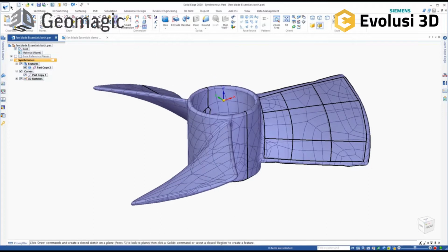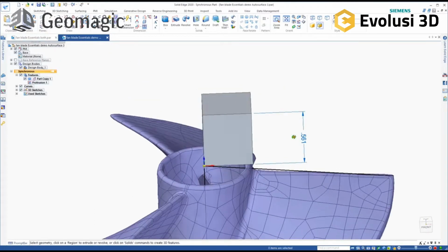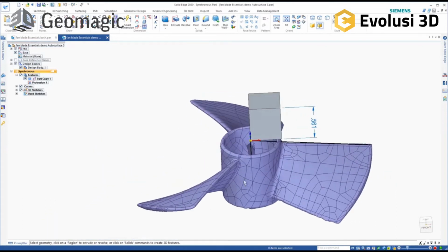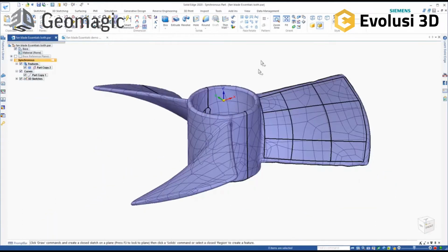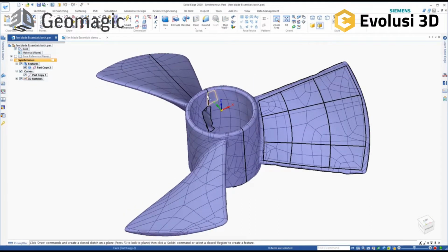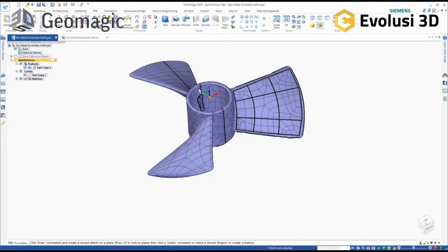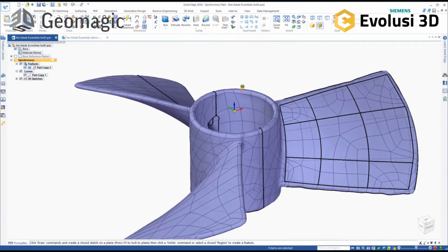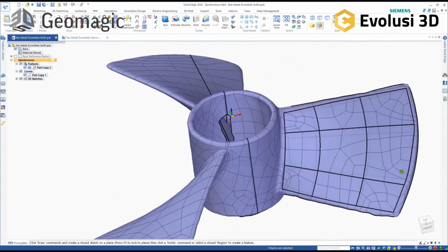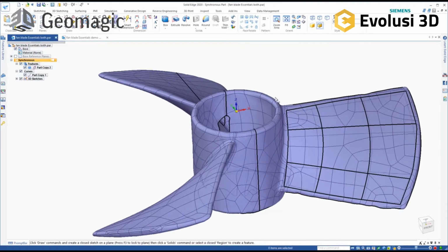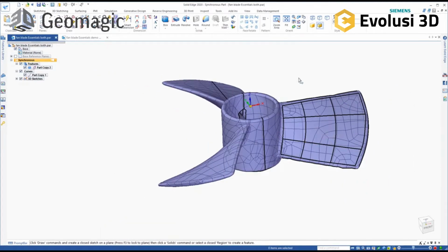And what I did is I went over to the application and imported each IGES file from Geomagic Essentials and brought them in and saved out the part. Then I came over and I took one part and I copied and pasted it inside of another. That way we have both the curves and the surface inside of the one workspace. So now you can reverse engineer using the Solid Edge tools in whatever fashion you want to.